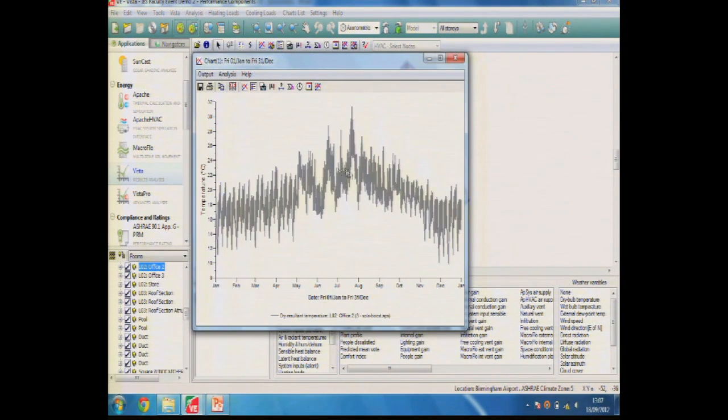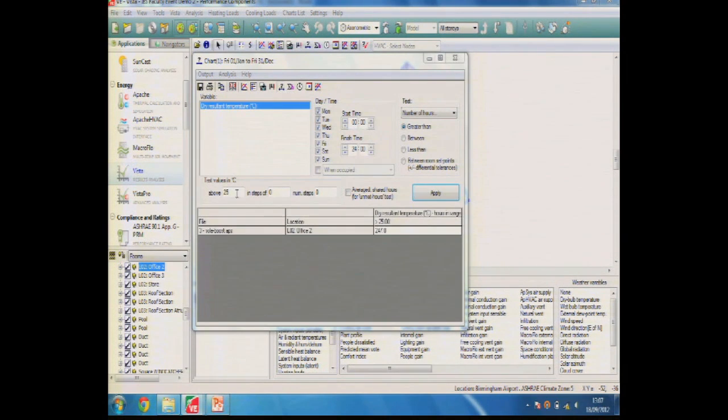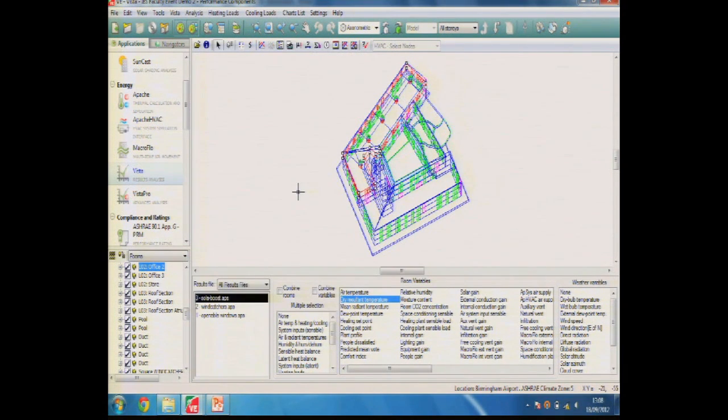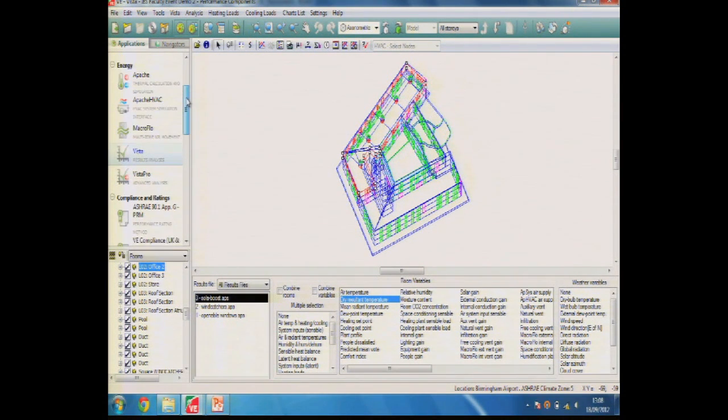So if I just look at the graph here, we can see that we're not exceeding 32 degrees C. And if I have a look at my range of hours that are over 28, you can see there 0.9%, so we're within those thermal comfort boundaries. And I should reiterate here that I have actually purposely made this a very heat gain intensive space just to show the potential for our natural ventilation strategy.